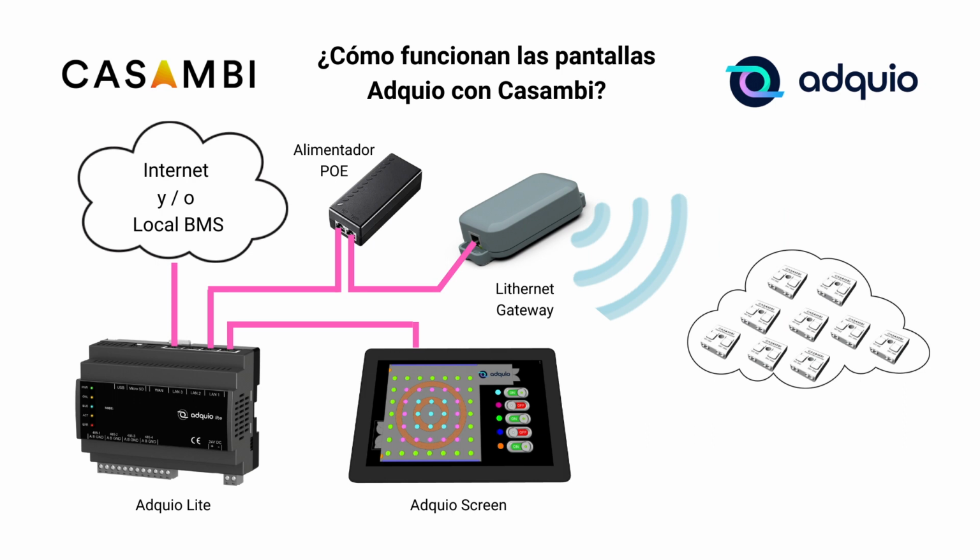In addition, in another of the LAN ports of that Adquio, we will connect a PoE power supply, which will provide current through the network cable to the device behind it, in this case, the Ethernet gateway. In this way, Adquio in a network port has a connection to the Casambi network directly and locally through the Ethernet gateway, and through another network port, it has a connection to the screen that allows controlling that Casambi network. Obviously, if instead of putting one Ethernet gateway, you put 16, you would have direct control of 16 Casambi networks. There is virtually no limit to the number of Casambi networks you can manage.